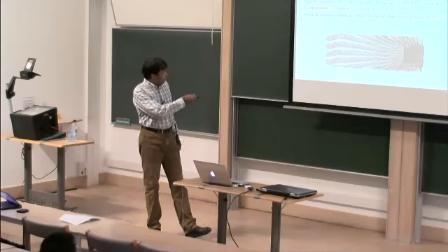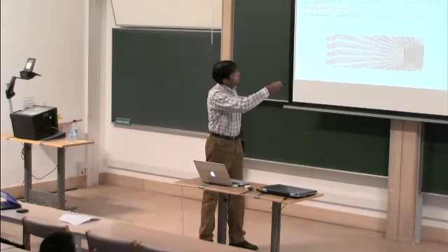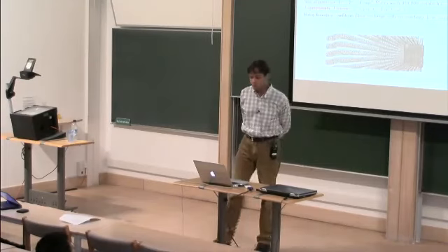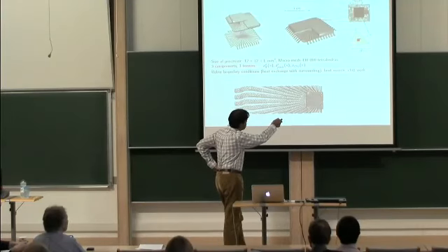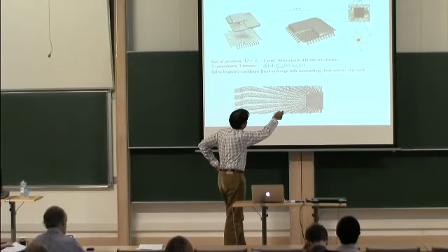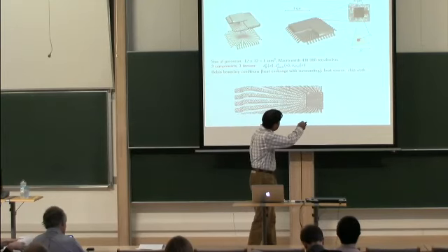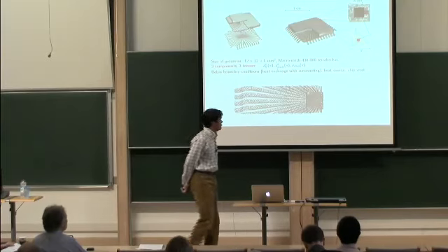And within each of these macroscopic tetrahedra, which is depicted here, we have a so-called sampling domain. In some literature, it's called representative volume elements, which is of size much smaller. Typically, the size of this box is related to the size of the microstructure. Okay, and we would like to test the microstructure in this sampling domain.